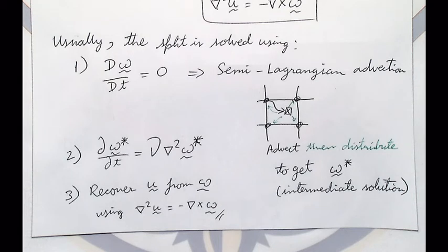And for omega, omega is also 0. Not necessarily. Actually, in a free flow, the only source of omega is the wall. If you have uniform flow, there will be no vorticity unless there's a wall to generate vorticity. So vorticity at the wall is non-zero, and figuring out what this non-zero value is a problem.